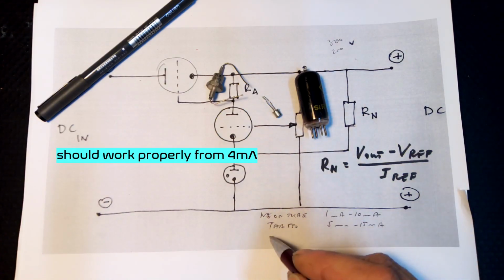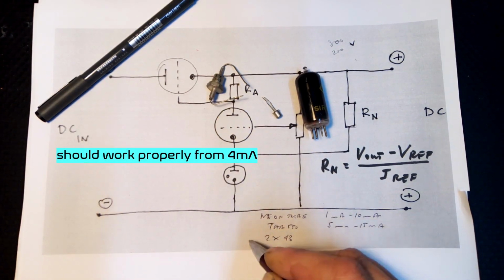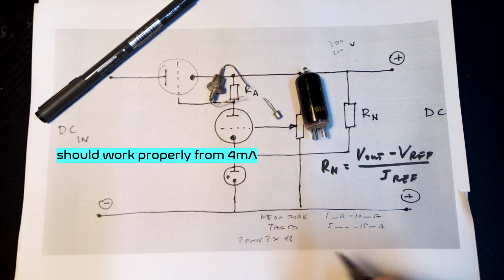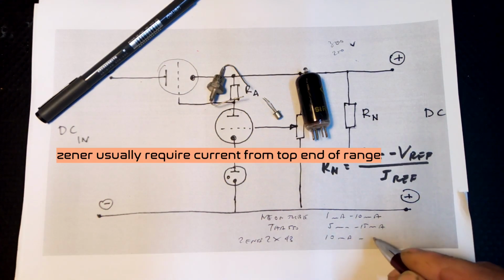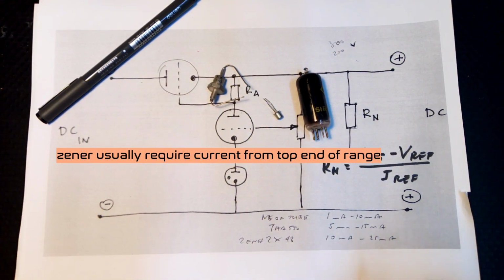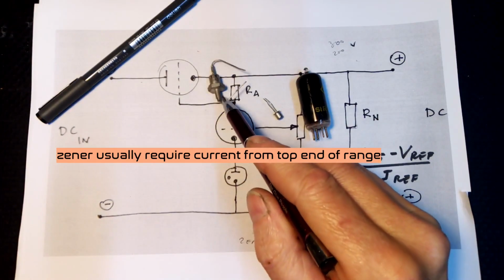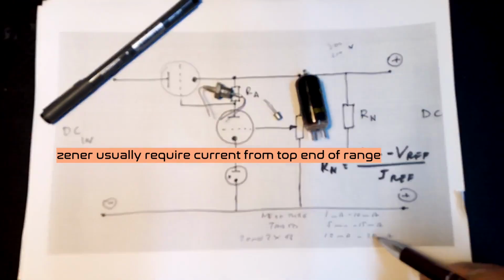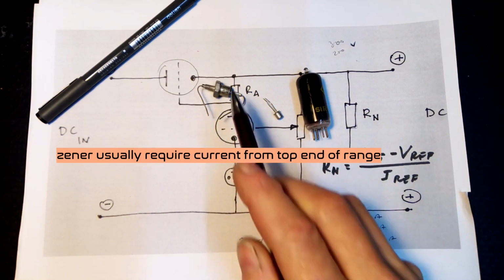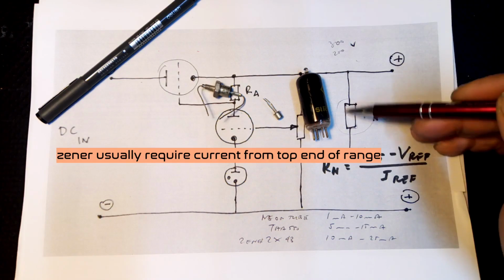And for this ZX43 Zener, it is 10 milliamps up to 25 milliamps. Even more, with a heatsink it can go much higher, but the problem is always dissipation from this element and also from this resistor.